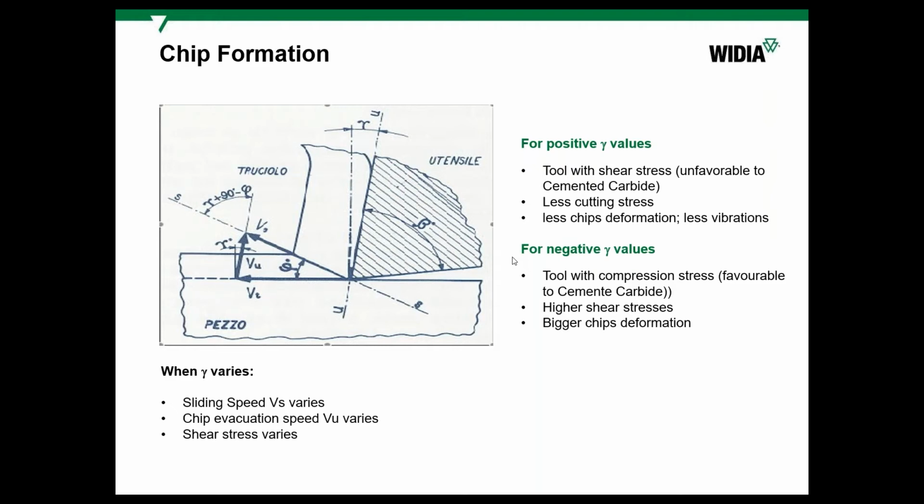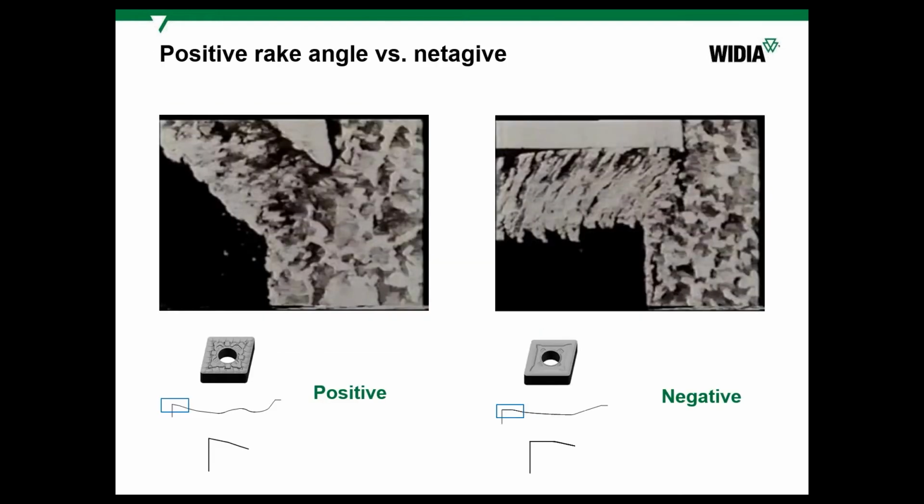And usually carbide is afraid of any residual stresses or bending stresses, but it likes compressive stresses, like cast irons also. You can compare it with these materials. And with negative inserts, carbide usually feels better than in positive inserts. If we talk only about geometry, generally the cutting process of positive inserts is for sure much better, easier to cut if conditions are stable.